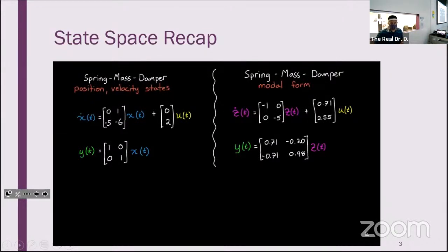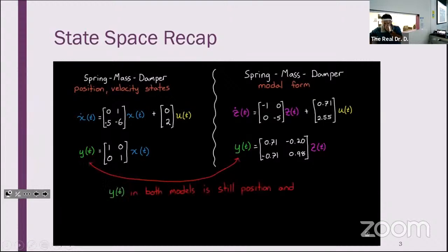to us. However, since the states are no longer defined as position and velocity, the C matrix needs to change if we want to keep the outputs position and velocity. In this way, we can see the benefit of the output equation. We're not forced to output the states exactly as we define them, but rather have the ability to linearly combine them into variables that we're interested in.